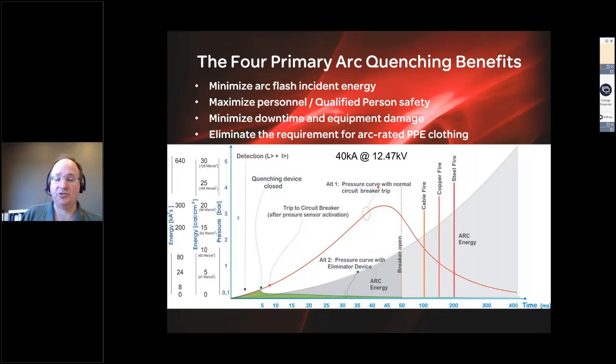So if you're within the arc flash hazard boundary, there is still that risk associated, which is why PPE is required, and also why the NFPA 70E will never approve PPE above 40 calories per centimeter squared, because even if we can protect you from the burn, we cannot protect you from the blast, the sudden pressure change that occurs in these catastrophic events.